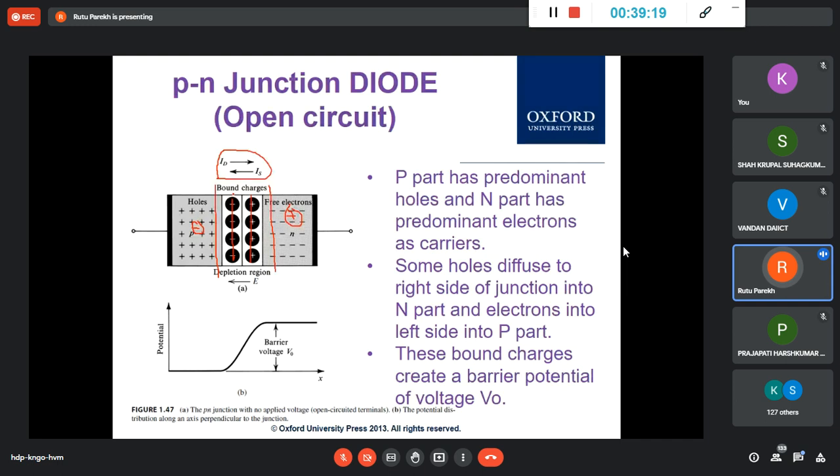to increase. So now that this is reduced, ID will increase again. And then ID will increase, right? Because in the second condition we took IS is more than ID. So if IS is more, then this depletion will reduce, which in turn will increase ID. So ID was less, and it will increase. ID will be equal to IS.